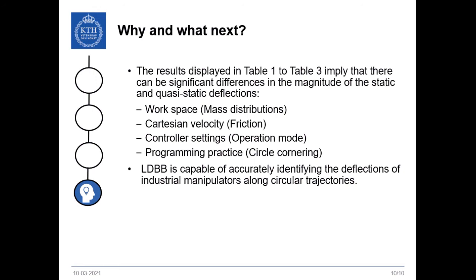The pragmatism in that sense lies in the possibility to calibrate an industrial manipulator task-dependent, that is, for the relevant portion of its workspace, with loads in the magnitude of the task, rather than workspace-dependent. This makes compliance calibration potentially cheaper, faster, and more accurate.